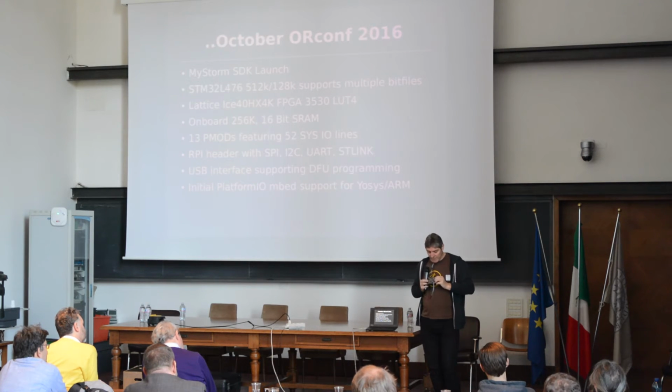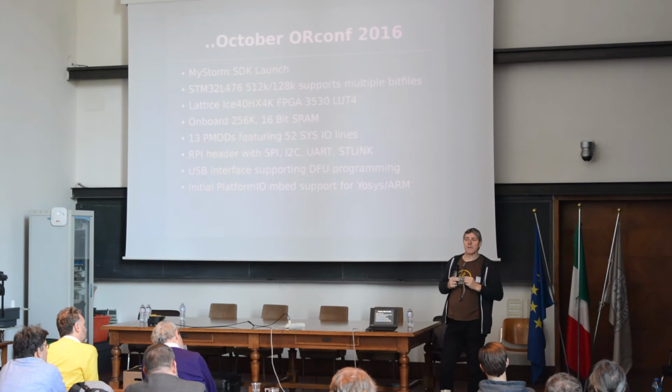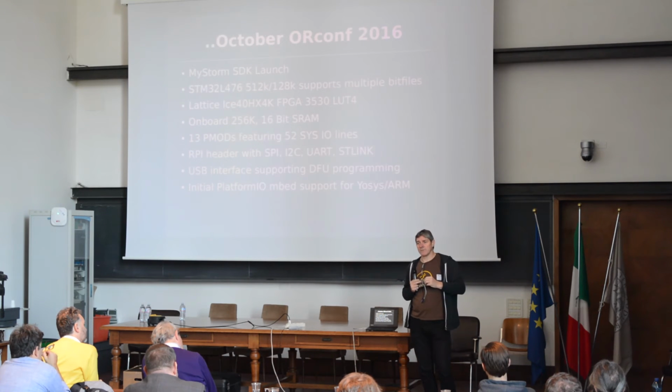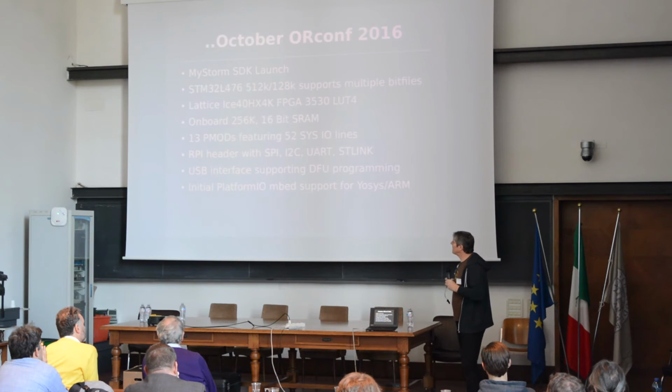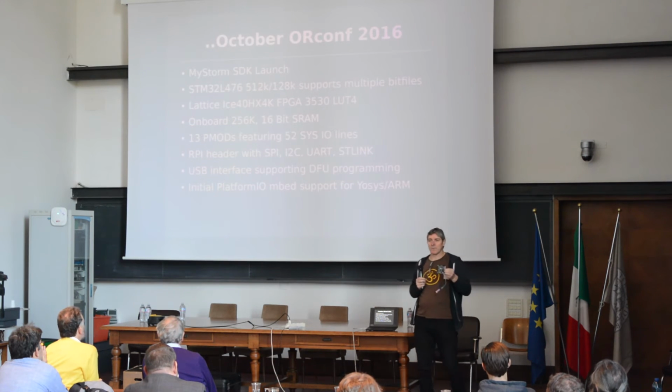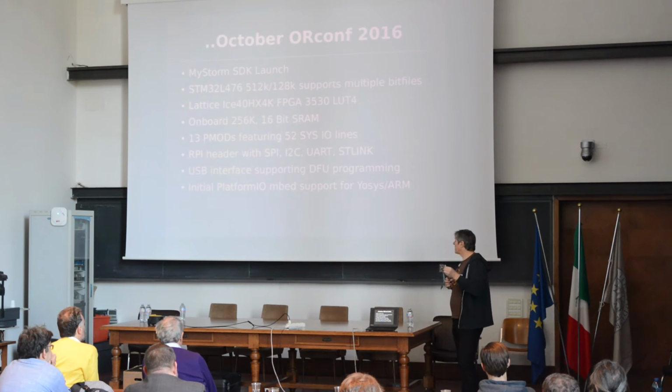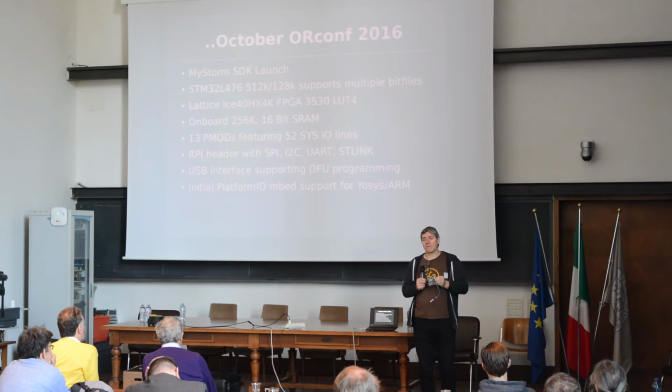Inside, from an I/O point of view, we have a number of other features. We have an Arduino pinout that is connected to the STM32, so folks coming from that kind of environment can take advantage of that if they have shields, etc. And this microcontroller has 5-volt tolerant IOs as well, which is really handy in that sense. In total, we have 13 PMODs, some of which are single PMODs, some of which are double PMODs. So there's plenty of I/O. We've got 52 SysIO lines coming out from the FPGA.